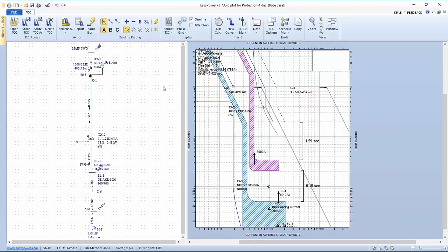We talked arcing tick mark, 85% and 100%. One of the things the tool does for us automatically is compare 85% versus 100% arcing current. And that comes into play when we have a breaker adjusted. So I've hovered over this curve, which gives me the dial settings. And again, I'm looking at BL3.